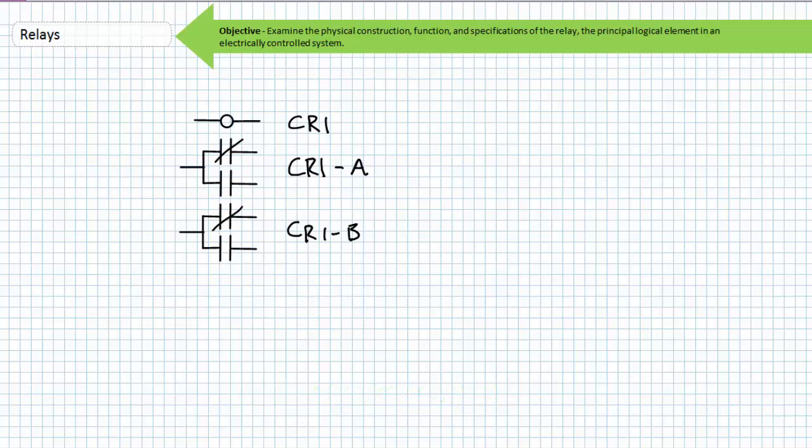I'll show you some super handy organizational techniques in later lectures on ladder logic diagrams, but a simple technique in keeping your house clean is to assign a name to each associated contact based off the control relay. If control relay 1 has 2 associated contacts in use, the coil is called CR1.